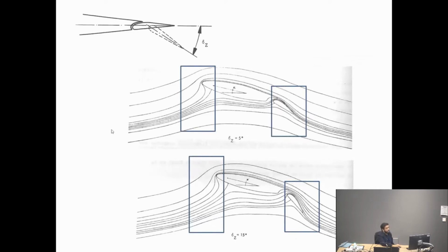First of all, the streamlines in front of the wing are deflected more upwards. And then towards the final section of the wing, towards the trailing edge, they are really deflected downwards. This combined effect results in an increased effective camber of the wing, which will give you more lift. So that's the idea behind having those trailing edge flaps.